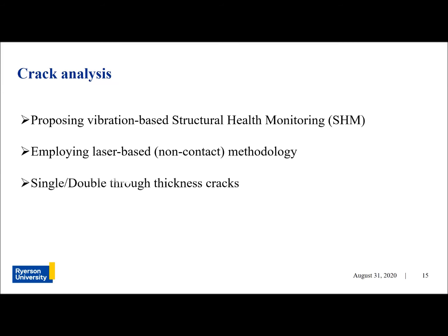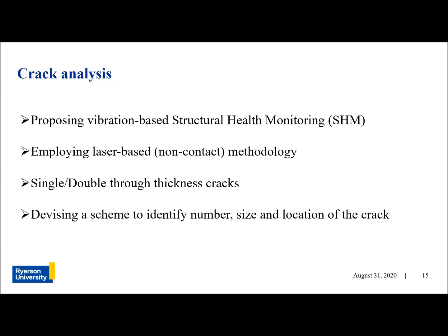The focus has been placed on single and multiple through thickness crack identification in 3D printed PLA beams. The goal was to devise a scheme to identify the number, size, and location of intentionally embedded cracks through the change in the system's natural frequency.